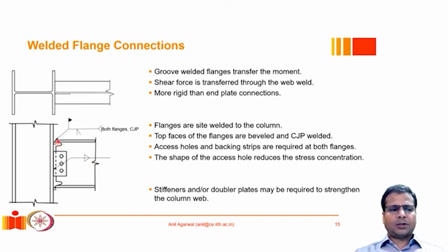So as I mentioned just now, this weld, which is the groove weld, it's a site weld. So generally site welds are to be avoided, but in this type of connection, site weld cannot be avoided, and appropriate provisions should be made for proper inspection and quality control for any site weld, in addition to increasing the factor of safety that we use for a welded connection.